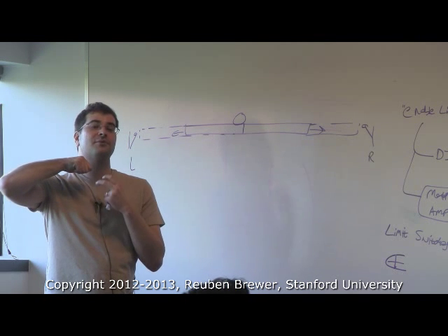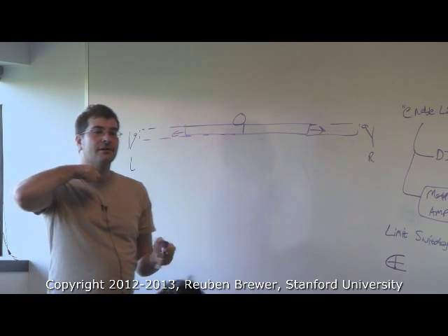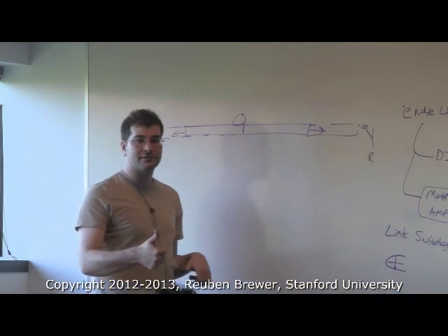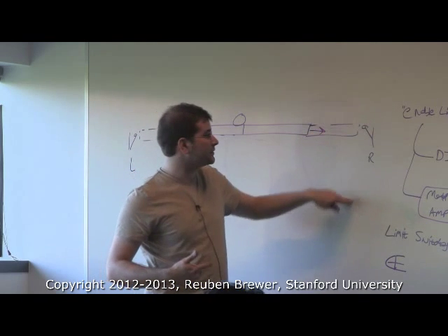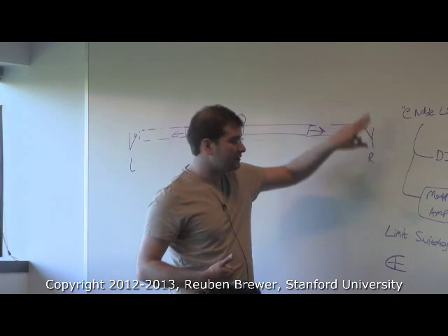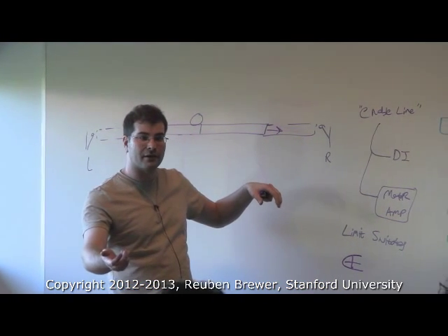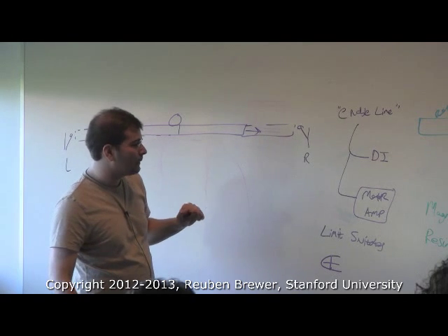Can I push it out, or does someone have to get an Allen key for the set screw that holds the knife? So for any type of safety issues with robots, you want counterbalanced, you want backdrivable, and you want multiple levels: the enable line to the motor amp, and the death switch that actually yanks the cord from the wall, via a solid state relay.